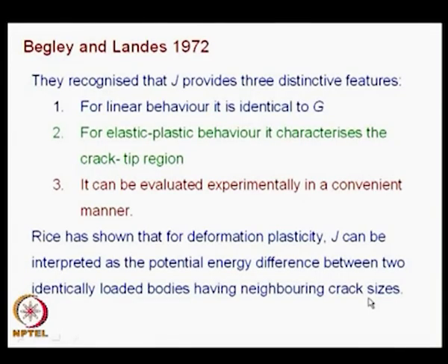See, the statement is subtle. In the case of linear elastic fracture mechanics, a crack can extend by itself and the analysis is still valid. In the case of elastoplastic analysis, the moment the crack grows, unloading takes place, and your analysis becomes not exact, because you are in the domain of using deformation plasticity theories.